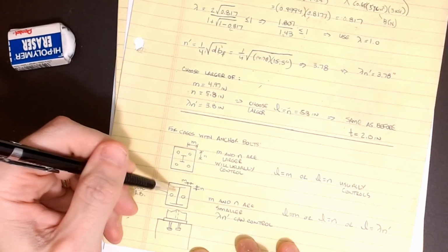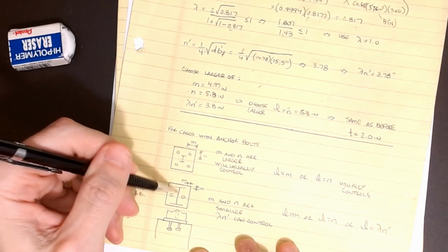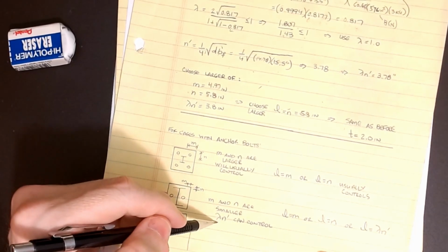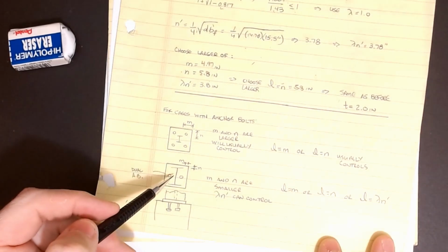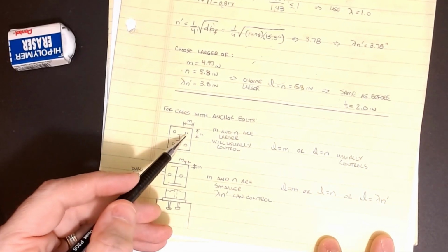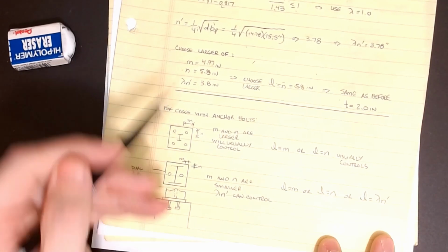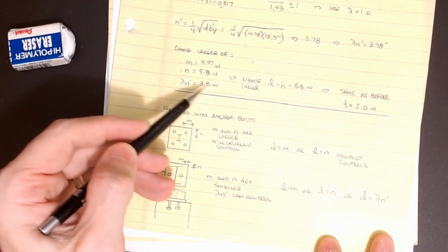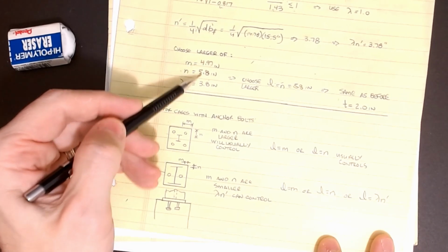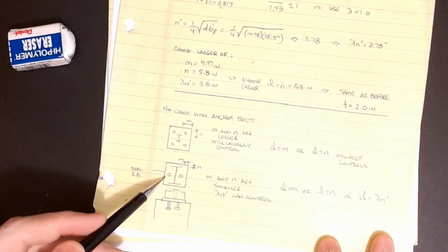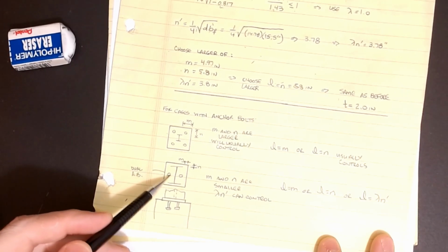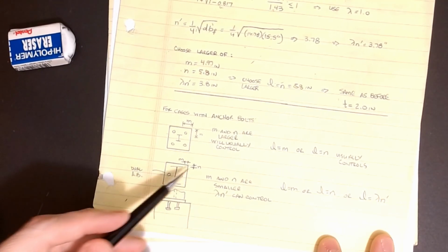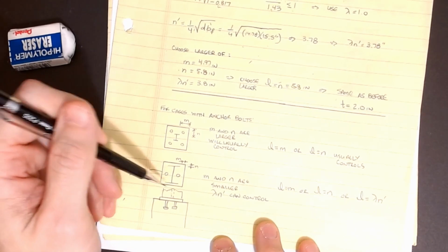if for some reason it is a smaller connection and your holes are here in the web, and I pull these plate dimensions in such that m and n are really, really small, those are the cases where the lambda n prime criterion can start to control. So this is why you still need to do the check, even where the bolts are outboard, but most of the time you can see it wasn't even really close when we did the calculations. It was 4.97, 5.8, and this lambda n prime was 3.8. It's a very small value. But if these two start getting really, really small, then this can start to control, and that's the phenomenon that usually happens where the bolts are inboard of the I-beam. We do this on very compact connections and footing bearing plates for those kinds of things.